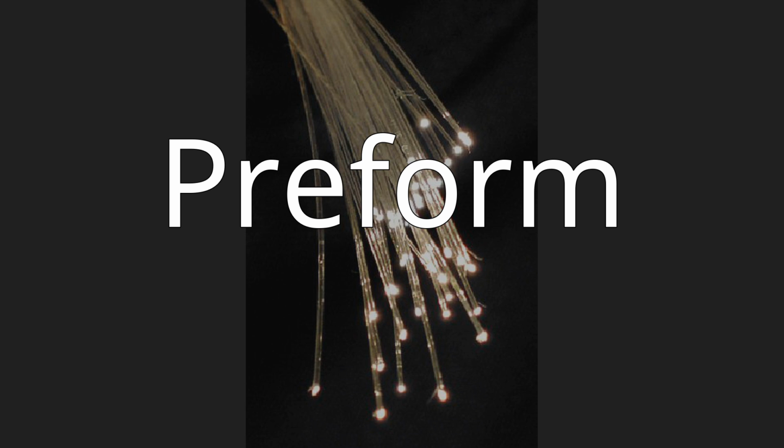particles. When the reaction conditions are chosen to allow this reaction to occur in the gas phase throughout the tube volume, in contrast to earlier techniques where the reaction occurred only on the glass surface, this technique is called modified chemical vapor deposition, MCVD. The oxide particles then agglomerate to form large particle chains, which subsequently deposit on the walls of the tube as soot.